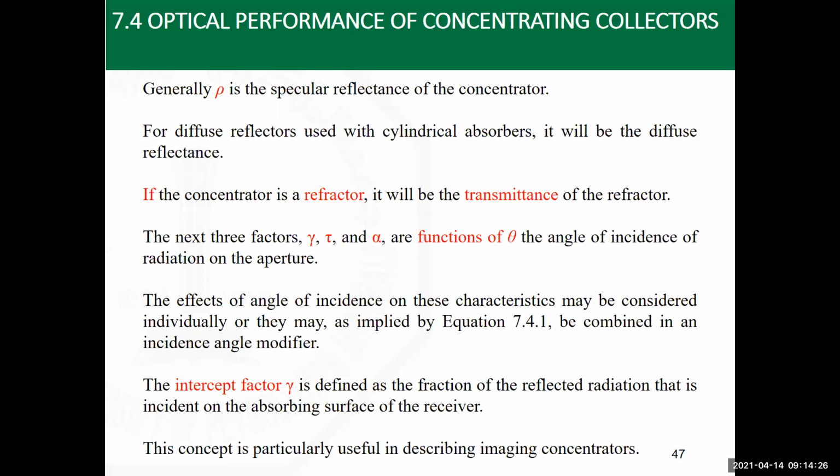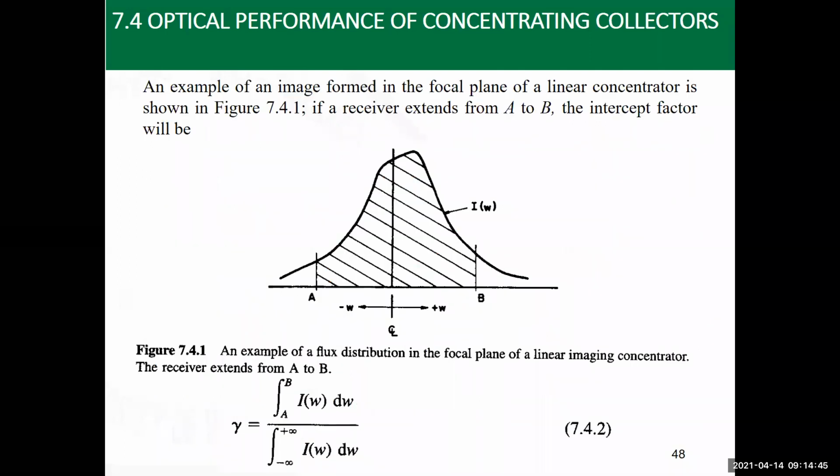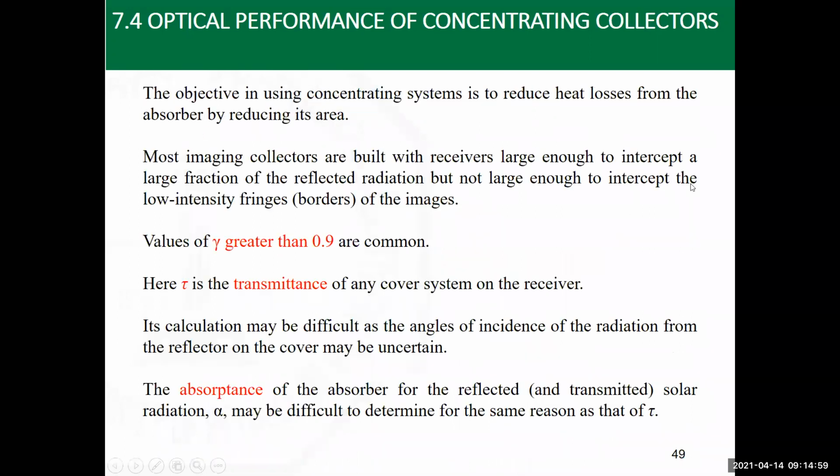How much is the reflected radiation based on the size of the reflector and the size of the receiver, which means that there could be an effective area for the reflector and the additional area would have less significance on the reflected energy. And that's why you might have a reflector which is limited in terms of width, and you don't need to extend the width a lot because addition of the width is not going to contribute a lot to the reflected energy.